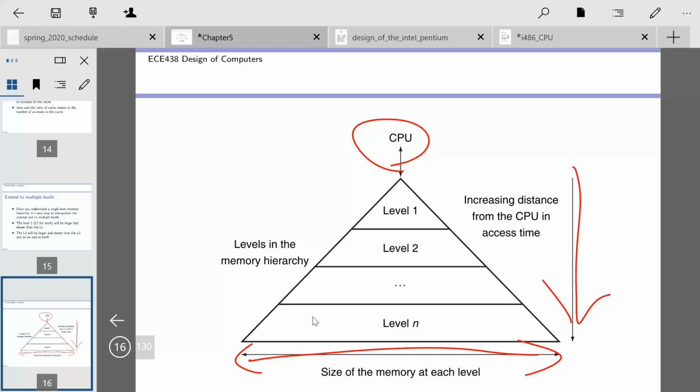Okay, and then of course your last level in the hierarchy is generally your main memory, and that is oftentimes off-chip DRAM. Now we are starting to play around with these different 3D and 2.5D packaging, where we're actually packaging DRAM in the same package, but still on a separate die as the processor, and of course that decreases the interconnection lengths, wire lengths between the processor and the DRAM, which increases the speed, and it allows our DRAM to run even that much faster.